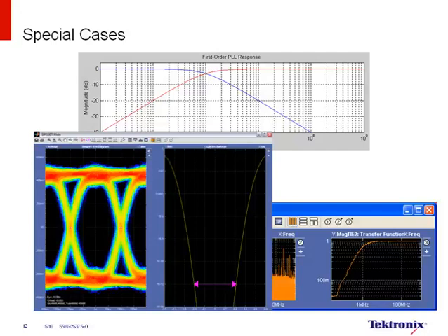So that's the top trace and the bottom right trace. The middle bottom is a BER bathtub curve. The way you want to think about this curve is that it is directly correlated to the eye diagram on the left. You'll notice that the eye closure is not the same as the BER closure.